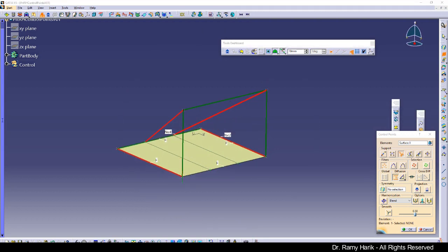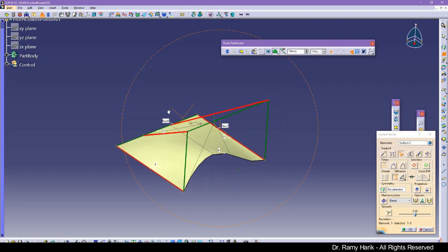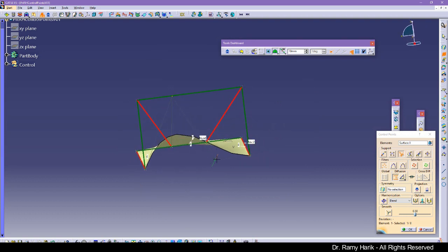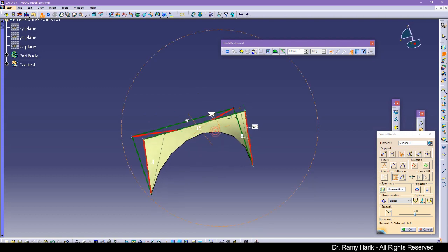So this tutorial is, I mean, this is not the right way to do the surface. This is more of the right way to explore how to create the surface. So we're going to manually manipulate this control point that we have in here, and we're going to move it up, as you can see. So this is moving it up, and then we're going to move it to this other side. Now this time we are going to move this one along this line.